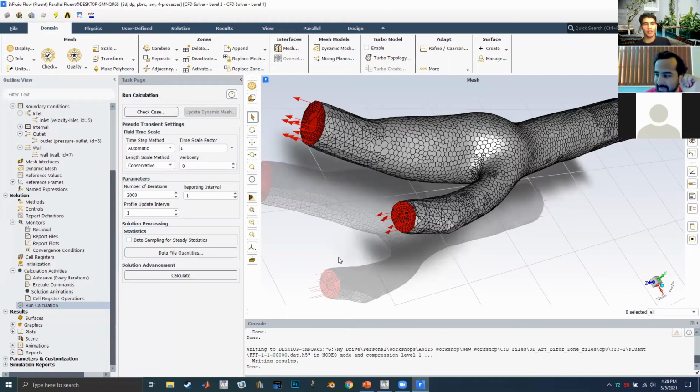Right. So a lot of eddies and low pressure disturbances. Yeah, eddies, low pressure zones. Often, if you have any small crevices, that can also lead to it. I know in my lab, at least, we have these bioreactors we make for our cell conditioning, and that geometry is not friendly for a steady state solution. It'll always start oscillating because we get these little vortices that start shedding on some areas. So for that, you always have to go with transient. You can't go steady. Okay, thank you.